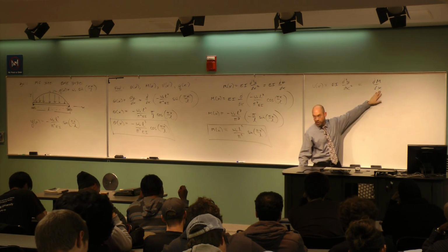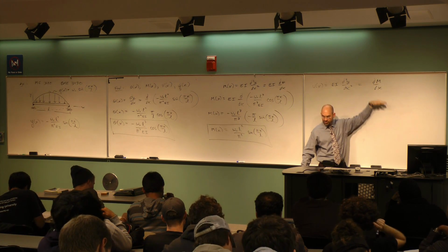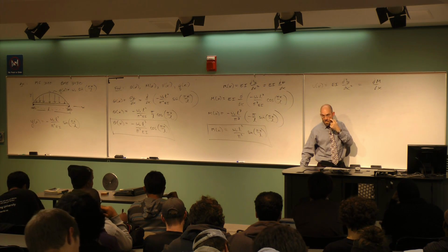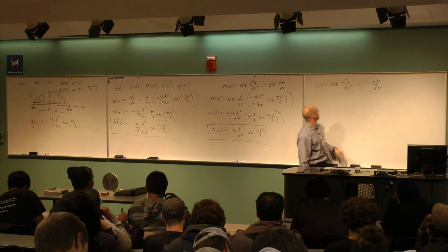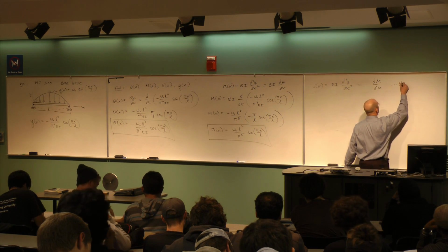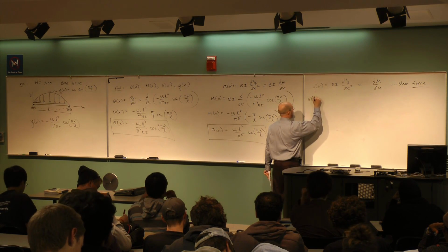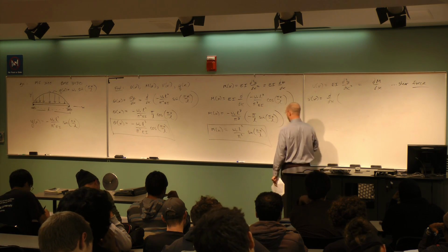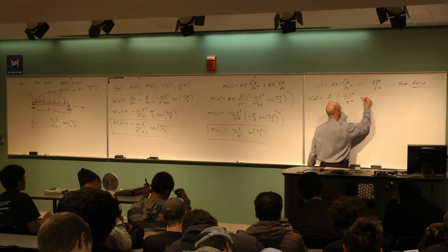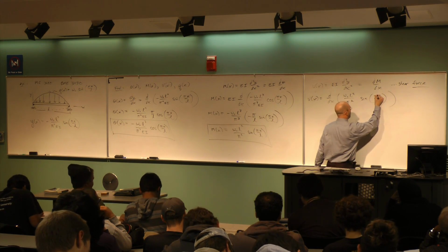Okay, and you can do a sanity check on the units, right? Force times distance, derivative with respect to x, knocks the units down, one less. Units on this will be what? It's going to be force, right? So that's what this is supposed to be, shear force. Okay, so that is the shear force, just to be clear. So the units are force. All right, so basically we just need another derivative. So this is the derivative with respect to x of this answer right here: W naught L squared divided by pi squared times the sine pi x divided by L. Okay, this thing seems to be getting simpler as we go, which is nice.